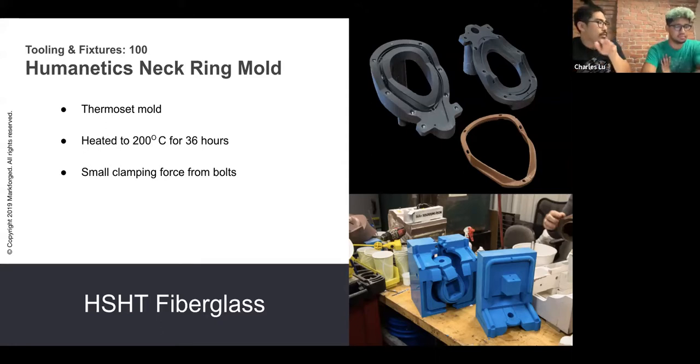What the HSHT does in this case: of our fiber reinforcement materials, it does have the highest heat deflection temperature. Correct. It's in the same range as Onyx, whereas the other fibers are in the 110 C range. This is 150 C. It's not like at 150 C it suddenly deflects. It's not going to lose all its properties at once at one limit. And this is proof that you can go above and beyond that. It also depends on the geometry, how thick the part is, and how much fiber you're packing in. Yeah, cool.